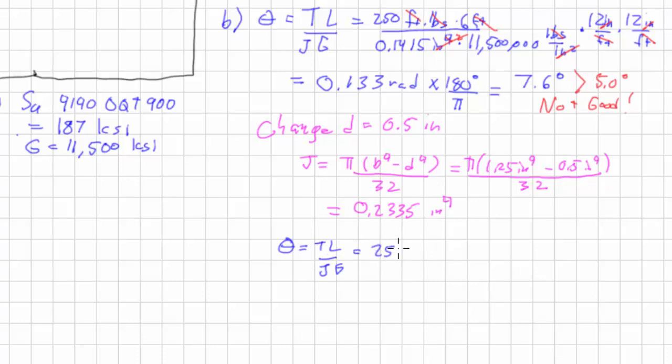Our new angle is, keeping everything else the same, 250 foot-pounds times 6 feet, all over 0.2335 inches to the 4th times 11,500,000 psi. I've done the units on this before, so I'm not going to worry about it again.